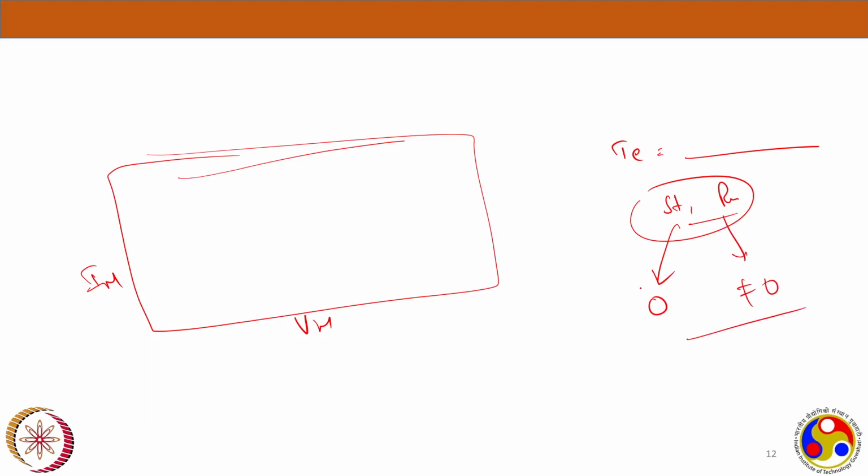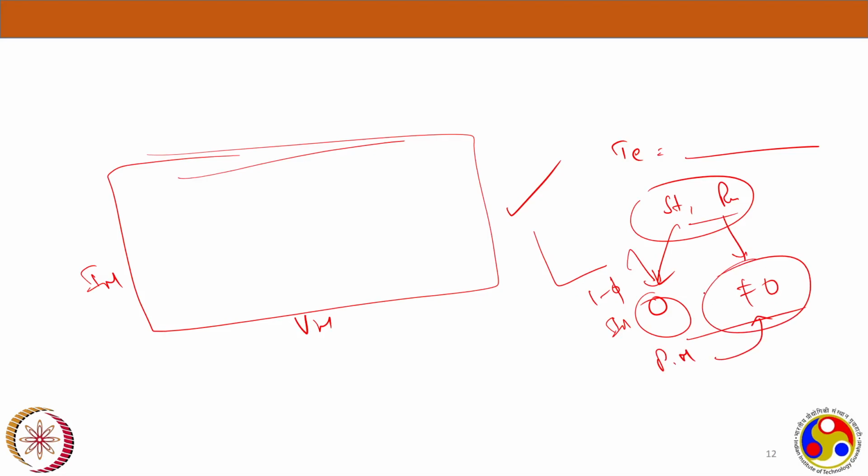So then we can justify that this particular equivalent circuit is behaving exactly as a single phase induction machine, because that's what we observed. In a single phase induction machine there won't be any starting torque, it won't rotate. We have to give it externally, and once we rotate it externally by any prime mover, it will pick up the speed, and during running condition you will have some non-zero torque. So that we will see even more clearly next week. We will have a good discussion, and now the time is not there, it's already 8 o'clock.